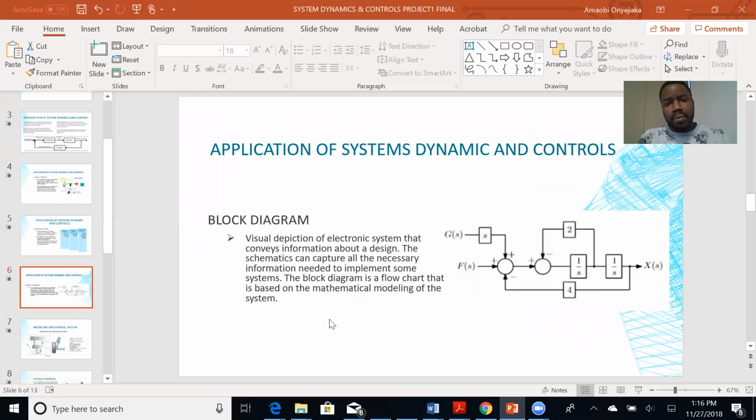Again, this is another example of a block diagram. In this particular case, we're focusing on the transfer function and the input and output functions. Typically, when you model the mathematical equation to govern any motion, you then have to take the Laplace transformation to get into the s-domain. And from the Laplace transformation, you'll be able to derive the transfer function for that system. The transfer function is just a ratio that compares the output over the input. What are we achieving versus what we put in and what we want to achieve?